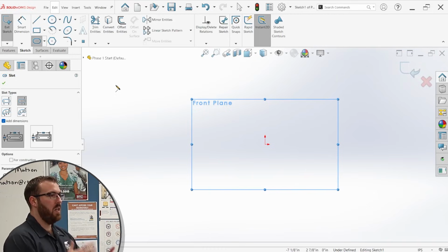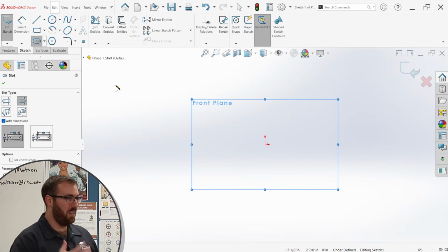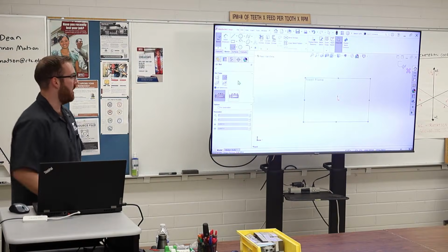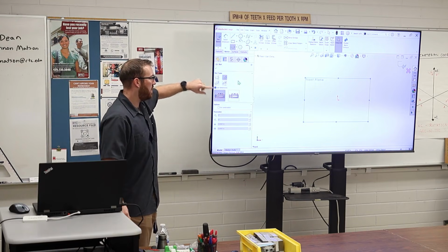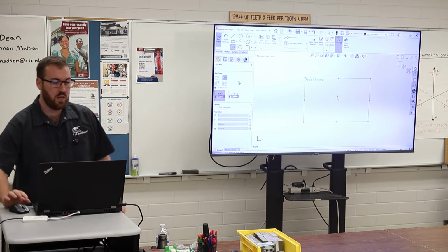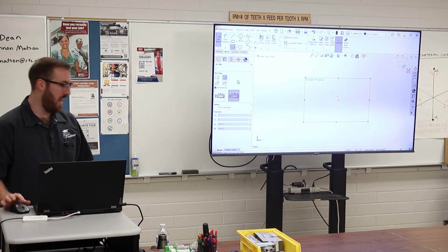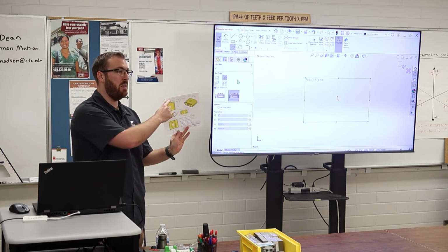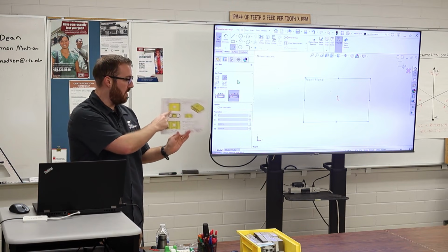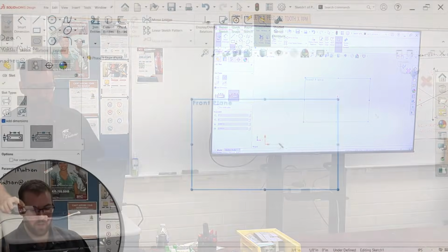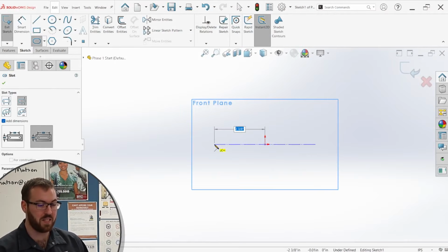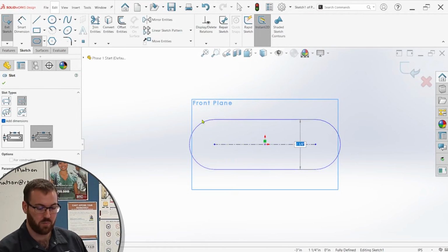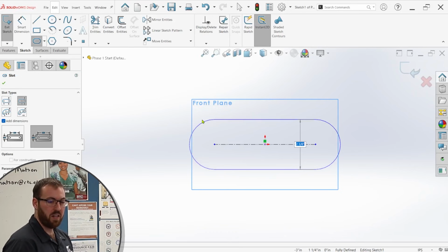Why not? Even though symmetry and mirroring comes up a lot, don't feel like you have to use it if there's a faster way. We also conveniently have the ability to add dimensions with a checkbox right here, and we can do that either center to center or end to end for the arcs. And that end to end is going to match up the dimensions that we have right here. We're combining a dimension from the top view, that 150, and we're adding that in to the front view. So I'll just start at the origin, come out. This is the center line, so we're not adding any dimensions to this just yet. But when I go to place this, here I have a dimension that I can add.